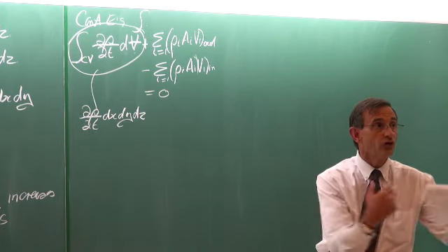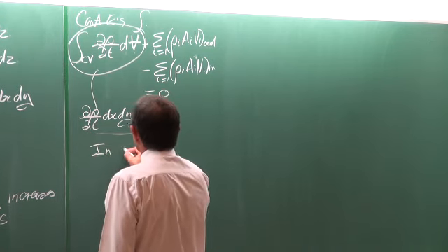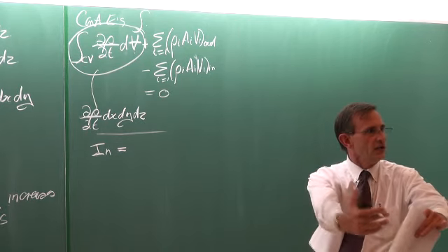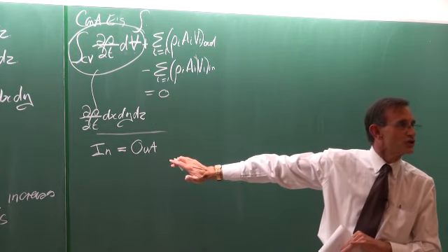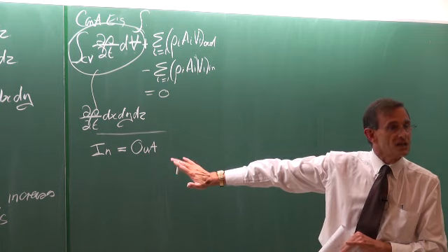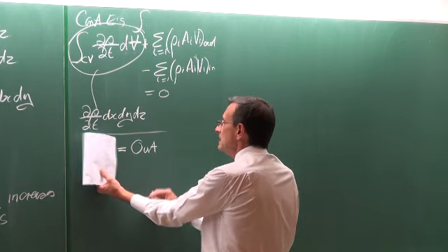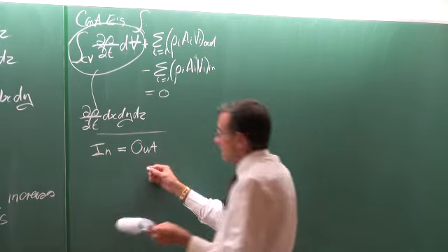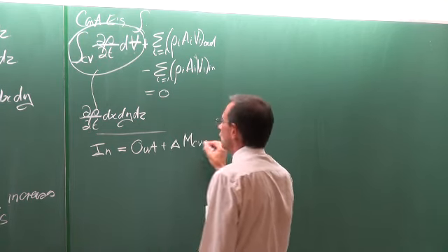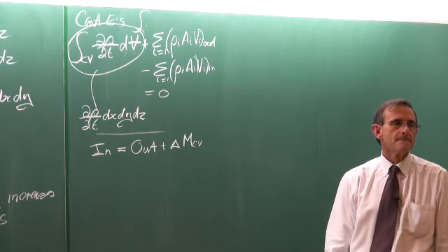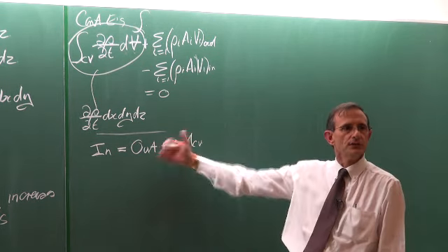Right, so if we now think of the continuity equation, if we say everything going in is equal to everything going out, normally that is true in steady state conditions. However, if it is not steady state, it should be everything going in is equal to everything going out plus the change in the mass of the control volume. Agree? So that is the real continuity equation.